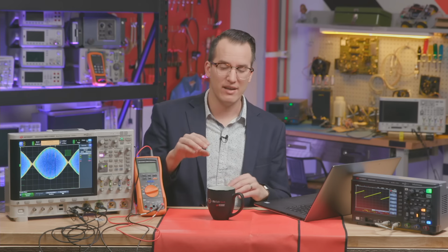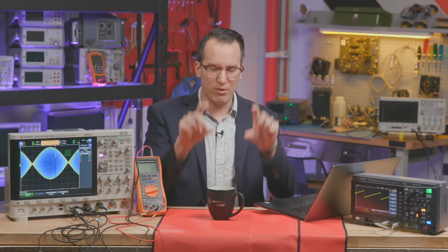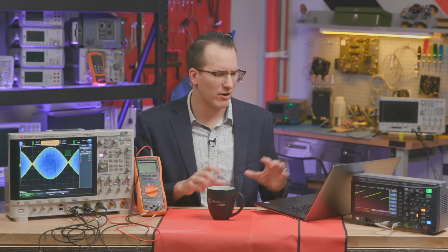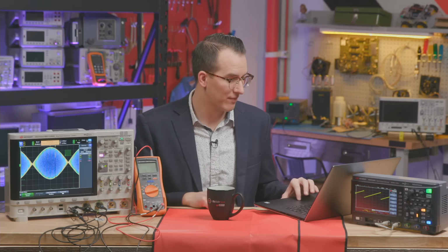The problem is when you have a DC offset, you still want to zoom in on that signal, but you can't necessarily move it to center screen and zoom in because you're going to start breaking the dynamic range of the scope, and then you get kind of weird behavior. So you can use a power rail probe with an automatic DC offset, and that lets you get right in on that without using AC coupling or a DC blocker. That's really the way to go if you're trying to measure power integrity on your power rails.